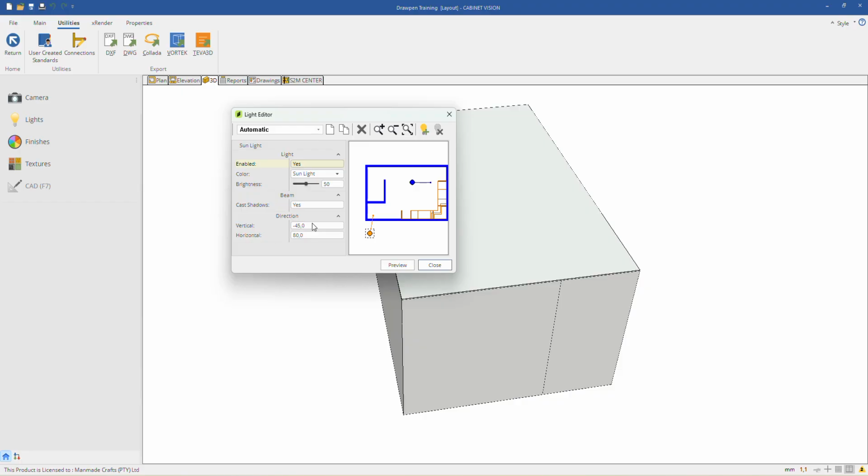So you can modify the direction there, or you can press here on the little dot at the beginning. Check here on the light. You see that little dot there on the line in the front? There you can click and hold, and you can drag and drop the horizontal direction that you want the light to shine in. You can't drag and drop it further. You can just change the angle. So pull it to the left or to the right, drop it. Now the sunlight is showing in that direction.